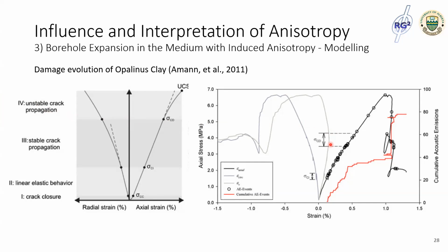It doesn't provide enough information to constrain the full elasticity tensor. But if you have opportunities to do more tests in different orientations, there might be a chance for us to look at how the borehole expands in different orientations in the ground, and that may give us some information to estimate the stiffness tensor.